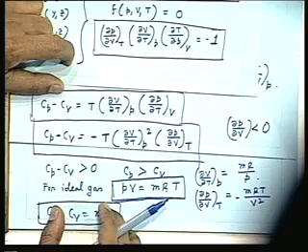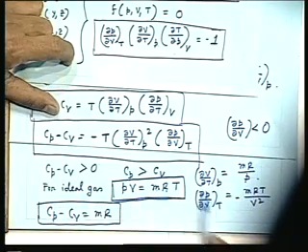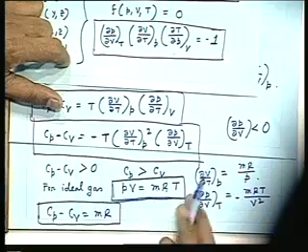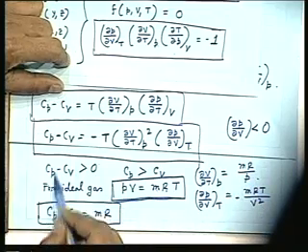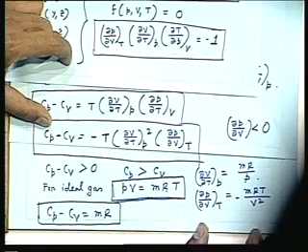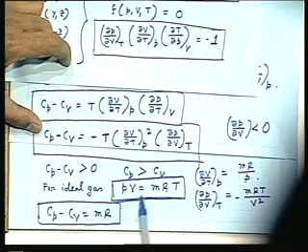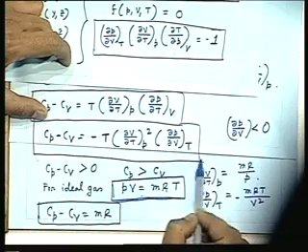This is a special case. That means if we have this equation between P, V, T, that is, if we know the equation of state for different systems, then I can find Cp minus Cv as a simple expression valid for that particular system. For an ideal gas, Cp minus Cv is mR. But this is the basic thermodynamic relation.